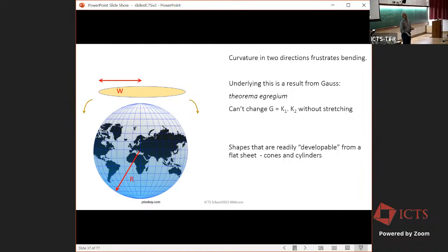You can control the thickness by controlling the amount of stuff in solution. The more diluted the solution, the thinner the object will be for the same conditions of preparation. And the faster you spin, the thinner the object will be. You got the picture? It's drying and spinning and flattening at the same time, and then you're left with a thin piece of plastic.